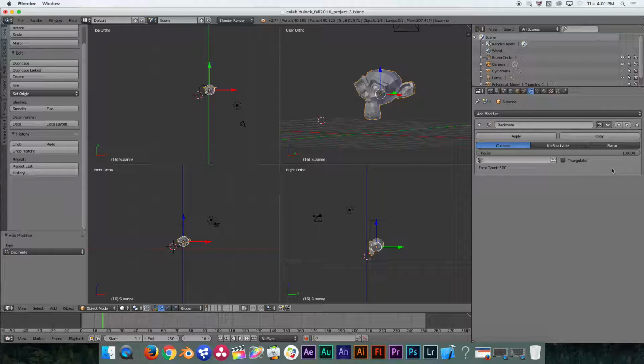And what decimate does is that it actually allows you to computationally reduce all the polygons in the structure down to simplify what the model looks like. So I can actually take this little slider bar that says ratio in my property panel, and you won't see any animation occur with this particular tool. Animation is specific to only certain things in Blender. This one is literally locked down to just controller changes. So with this one, if I click and drag on ratio and release, it's literally cutting down the amount of polygons that make up my final model. So the lower that ratio number gets, the more simplified the model looks.